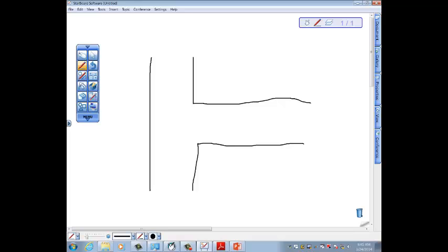So the top bars, which are the number 9, you're going to draw them at 9/8 inch thick, which I will not even attempt to do here, but y'all need to do it. And that top bar will come and curl around like in that drawing below. And you'll only see one of them because you're looking horizontally through it. So you're going to draw this line, and it's going to curve, and it's going to be 9/8 of an inch thick or wide.